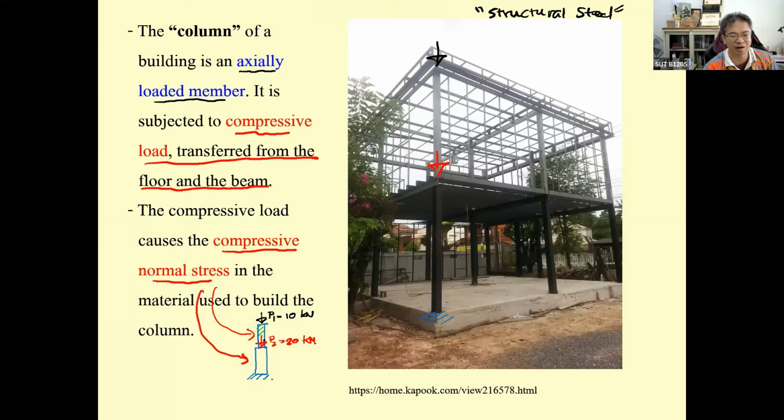The stress that occurs here, and the stress on the bottom one, can be determined easily by sigma equal to force over A. Under the normal operation, let's say you use your house as usual, the stress in the column must be smaller than sigma allowable.